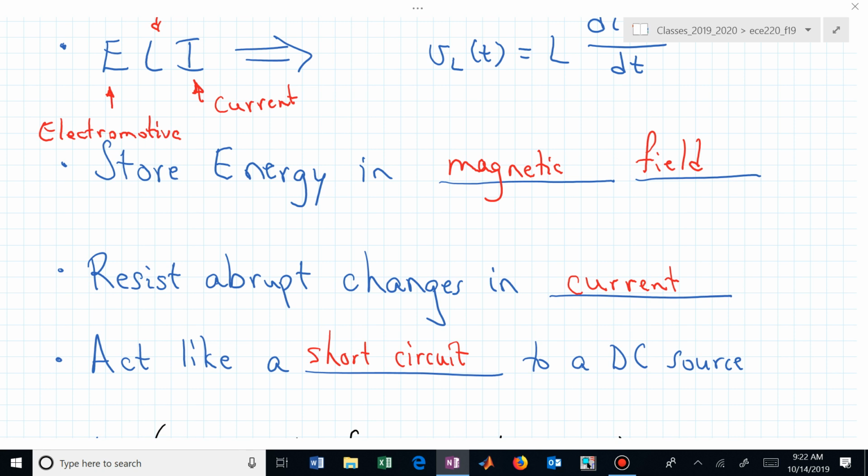So if I give you a problem and it has DC independent sources and it has a bunch of inductors in it, you can say, oh, I'm assuming now we're at steady state, or all the transients have died. So this has been in this condition a long time. Now you can just draw a wire across those inductors and you just have to solve your resistive circuit using Chapter 4 material, which you're studying for frantically to get ready for exam number 2, which is Thursday. Had to take a commercial break.